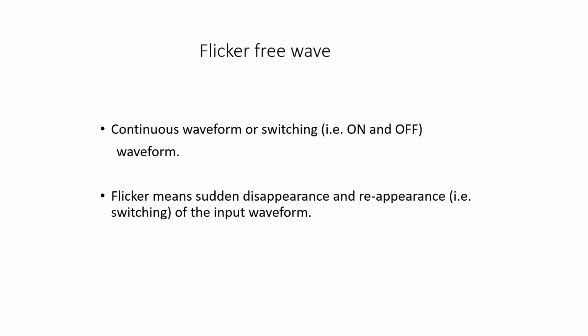The sine waveform applied to the vertical deflecting plates is synchronized with the ramp. The waveform of sine waves is displayed on screen with respect to time. So, to obtain a stationary waveform, the horizontal sweep frequency and the vertical input frequency signals must be applied to the corresponding deflecting plates at the same time. That is, they are to be synchronized. Synchronization has to be done to obtain a stationary pattern.